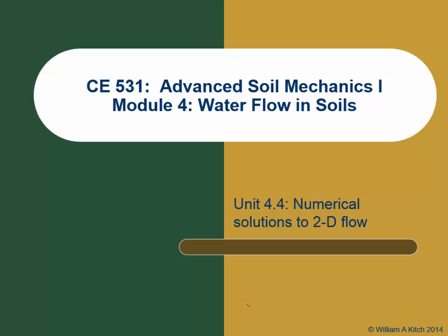Doing flow with finite element programs is easy because doing flow is really simple. The boundary conditions are simple. The model's simple. It's probably the one kind of finite element analysis that anybody can do. You don't have to worry too much. Doing stress, strain, and soil interaction problems with finite element, that's really hard. It's easy to make mistakes. If you don't do a good solution, it's bad. But flow is really easy, so it's a really good tool to use. And we're going to turn you loose on doing flow in 2 dimensions with finite elements, almost to the black box without you even having to know anything about finite elements.